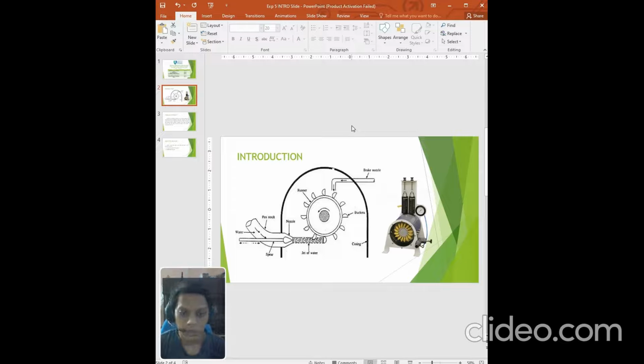The Pelton turbine has a fairly simplistic design. A large circular disc is mounted on some sort of rotating shaft known as a rotor. Mounted on this circular disc are cup-shaped blades known as buckets, evenly spaced around the entire wheel. Generally, the buckets are arranged in pairs around the rim.